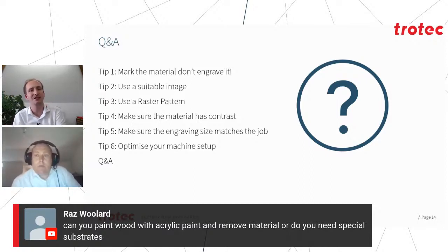Another tip I quite often use is, if you can paint it in advance, then I'll add further protection to it, whether that's a low tack tape, which again can just help concentrate the laser energy into removing the material rather than spreading too much.